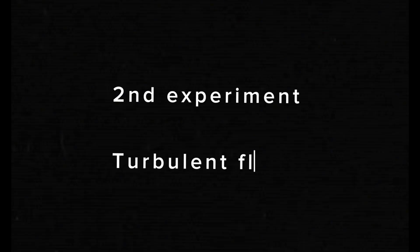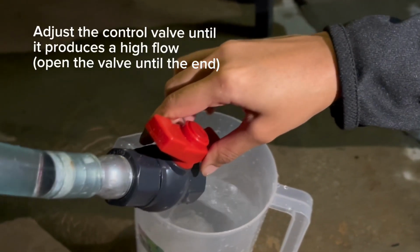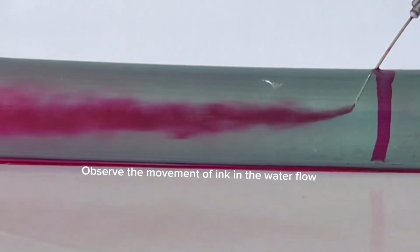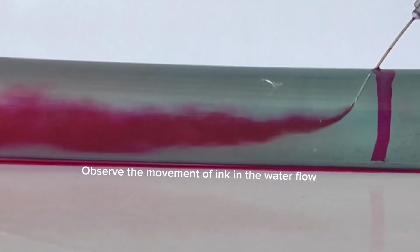Second experiment is turbulent flow. First, you need to adjust the control valve until it produces a high flow by opening the valve until the end. Then, record the time of water when it reaches 1 liter. Then, observe the movement of the ink in the water flow, you can see the turbulent flow.